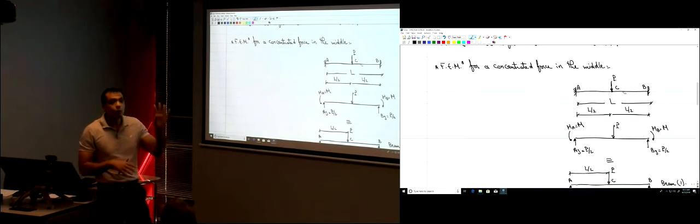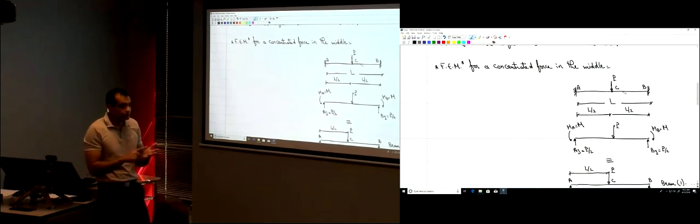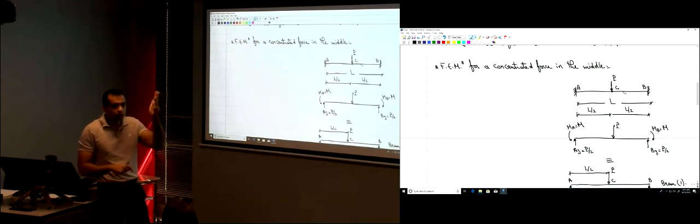I actually have 4 pieces of information that I can use. The deflection at A is equal to 0. The deflection at B is equal to 0. The rotation at A is equal to 0. The rotation at B is equal to 0. I know this information, right? I don't need all 4 pieces of information. I just need one of them, because I only need to know how much is the moment M.